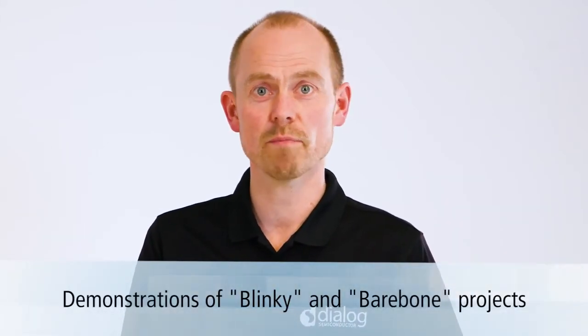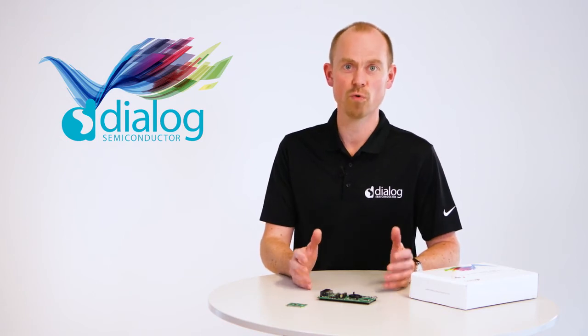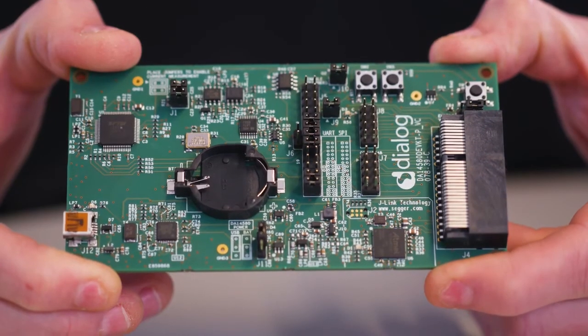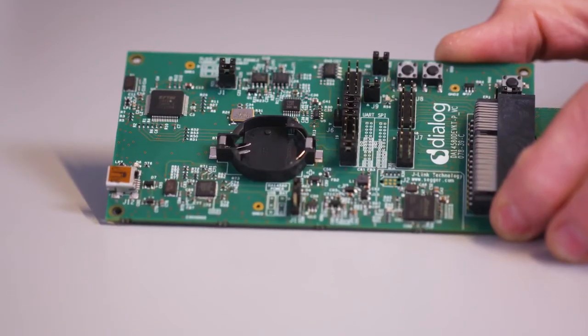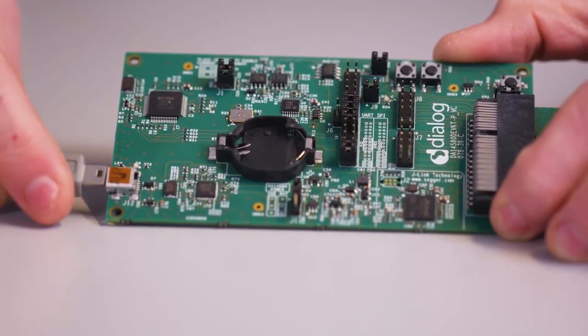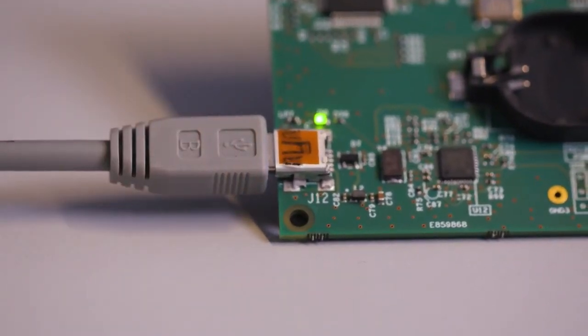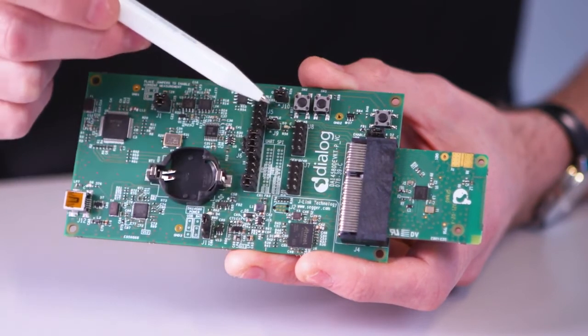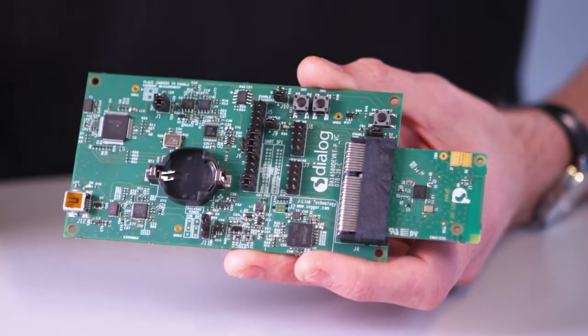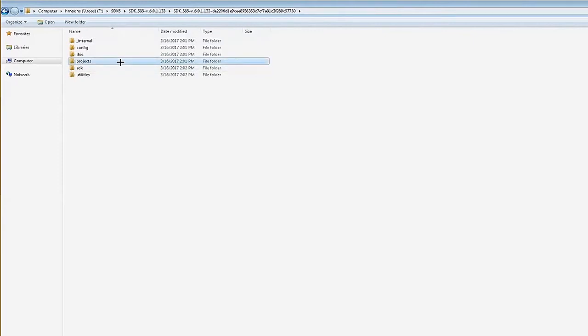Now I'll show you, step by step, a procedure to run the Blinky project. We use a simple project to test run the functionality of the whole environment. So the first step we need to do is connect the DA14585 Development Kit Pro to your PC. This is done by using the micro USB cable. Please make sure that the jumper J11 is set for the USB connectivity. And also check jumper J9 to connect the LED. Now open the Blinky project, which is in the peripheral example folder, like this.